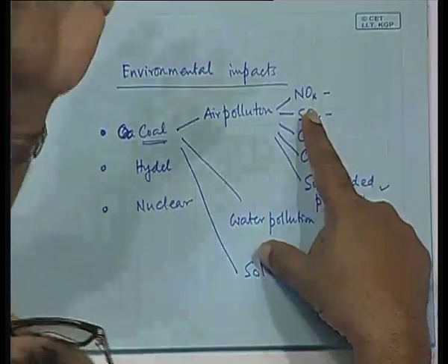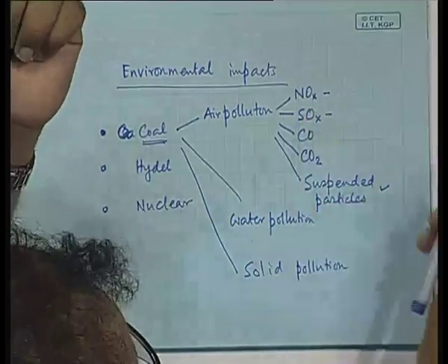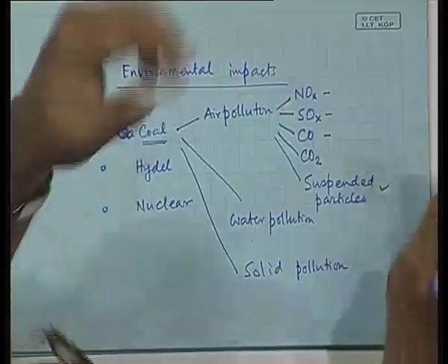Very difficult to do in pulverized coal boilers, relatively easier in the fluidized bed boilers, because in a fluidized bed you have small chunks of coal that is fluidized. Along with that, if you mix a bit of lime then that absorbs the SO2. So that can be used as a process. CO, it is just a matter of proper stoichiometric ratio. So CO production can be minimized unless there is a bad mixing of air. CO is not really produced.